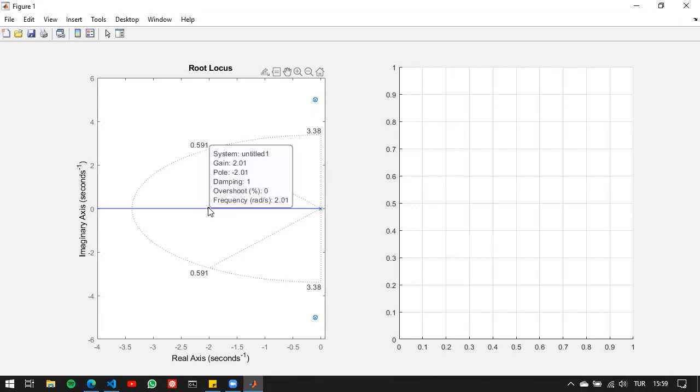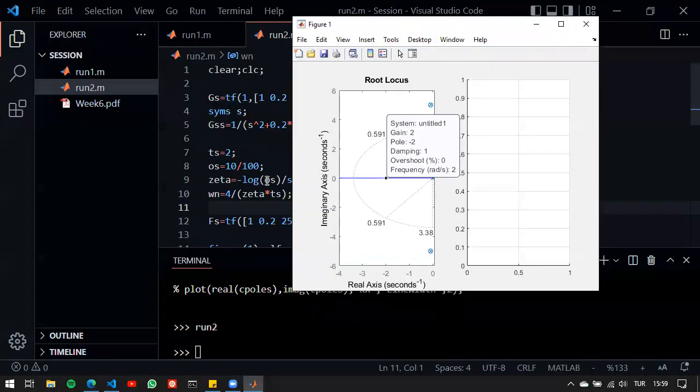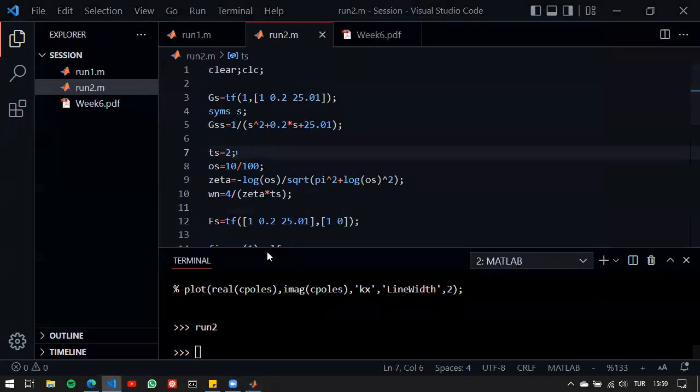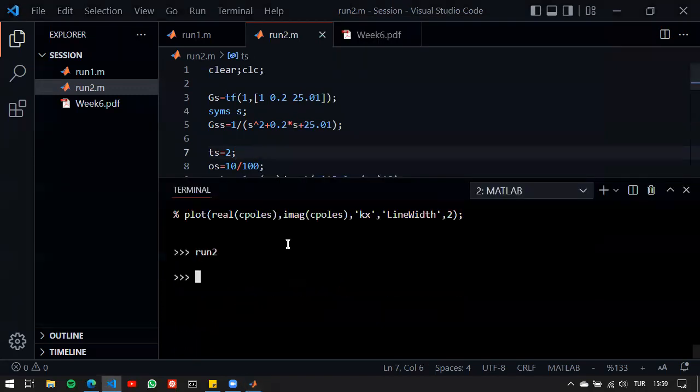And as you can see, as I move on the root locus, I basically have a pure integrator in the loop here. Therefore, if I have a closed loop with a p-type controller, I will get k divided by s divided by 1 plus k divided by s.